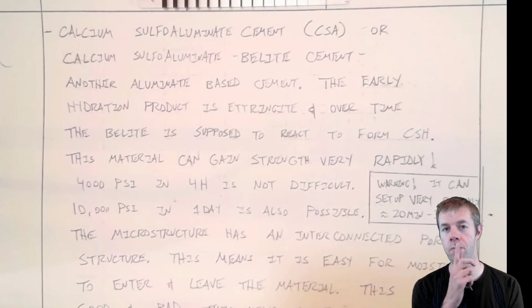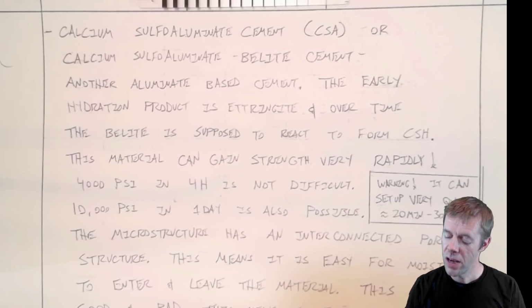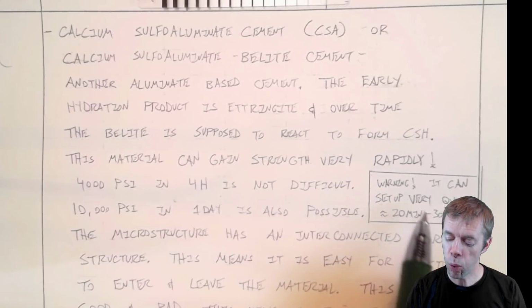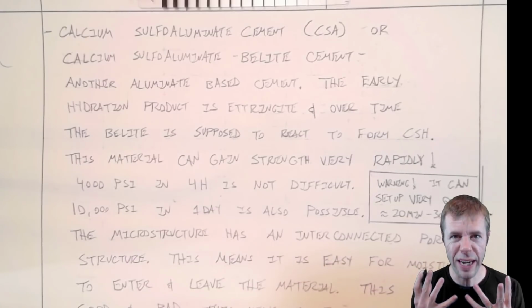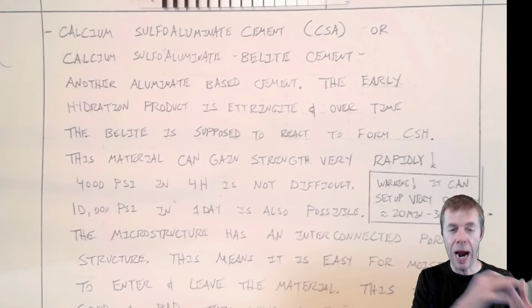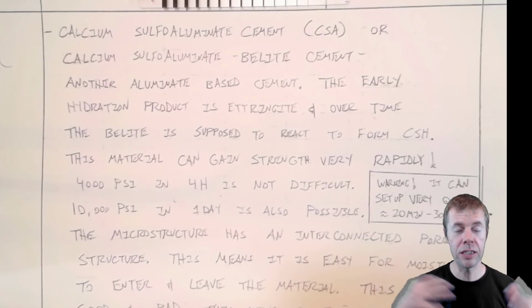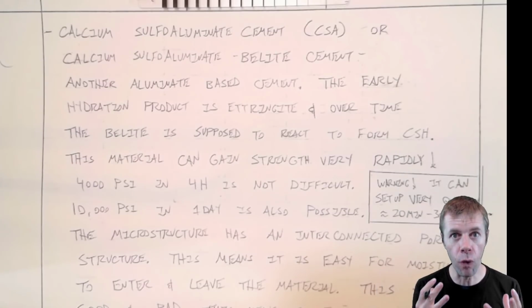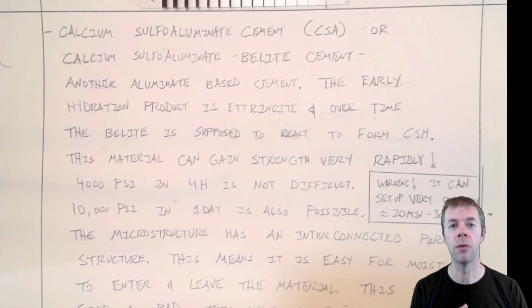There's a drawback. This stuff is rapid hardening, like crazy rapid. It will get super hard in 20 to 30 minutes. That means if you don't get it out of the mixer, in place, consolidated, finished, in the final form, you're in deep trouble. You're in big, big trouble.